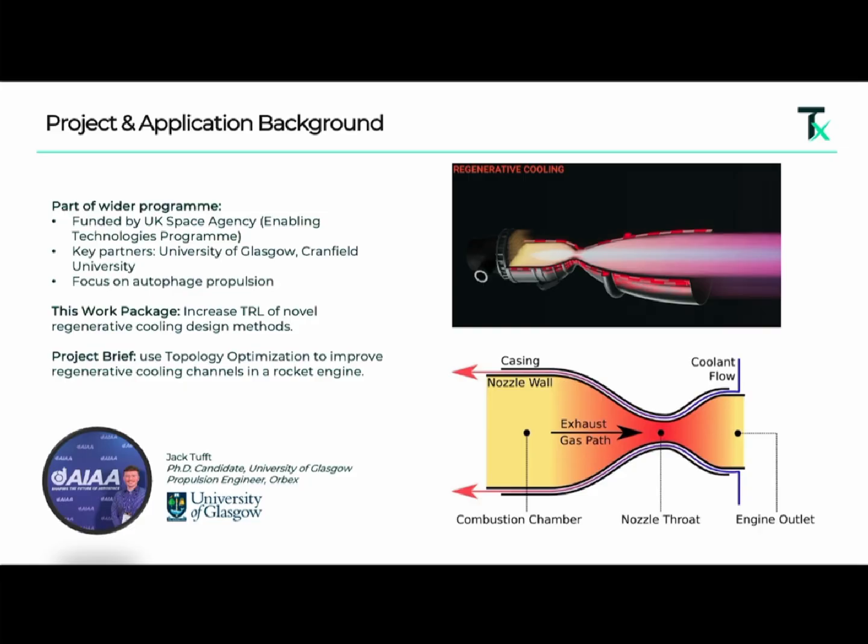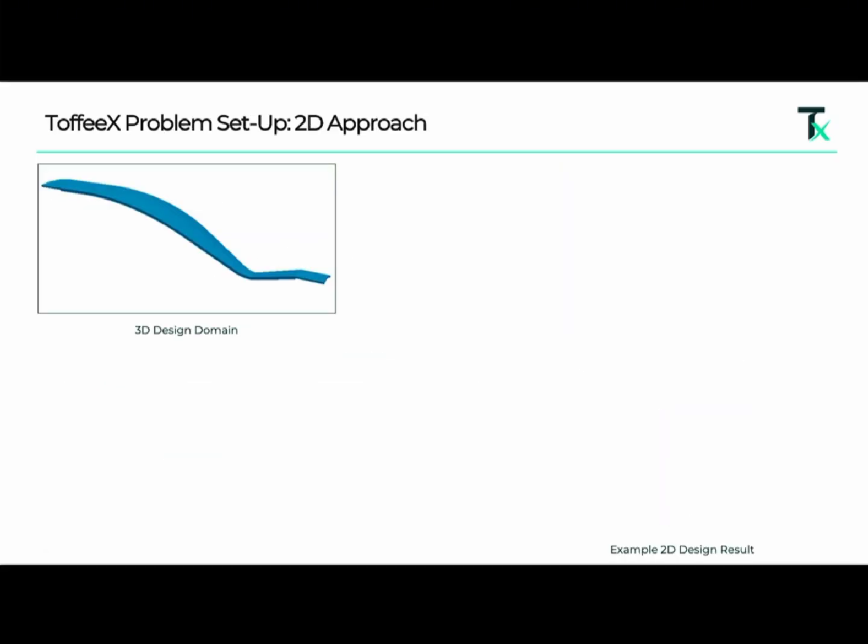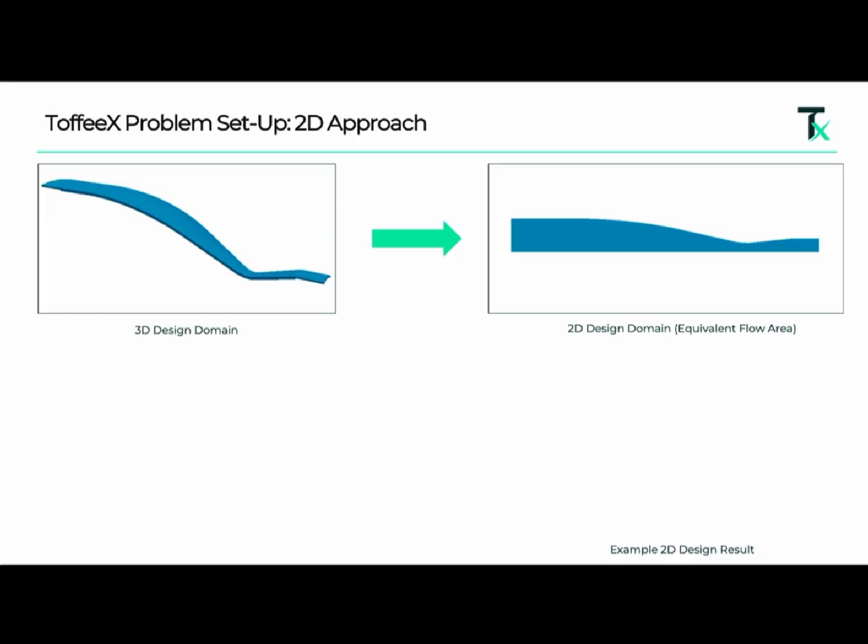And normally the way people do that is they run cooling channels. Using the fuel, they run the fuel through the cooling channels around the walls and then back up, and they inject the hot fuel into the combustion engine. And so this cools the walls, so that's good, and it improves the efficiency of combustion, so that's better. So he said, all right, I want to have a go at doing this. So he did a bunch of stuff.